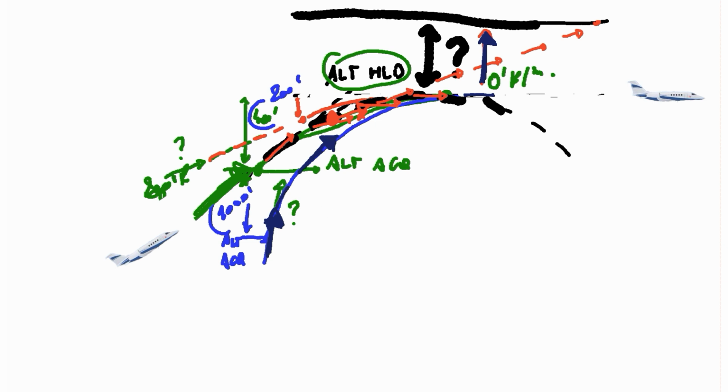Well, I should cancel a little bit of this drawing, because now it's getting a bit too much. So I was saying, it could be that at this moment in time, I made this change in selected altitude. So I changed the altitude from there to there at this moment, and the circle was this circle. Okay, so this circle is not intercepting the newly selected altitude. And well, how do I sort out the problem?